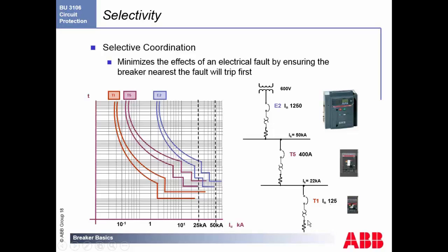Now, if this load down here has an issue, you don't necessarily want to take out the main breaker, because when you do, you are shutting power to all the equipment down the line from there. You can have several different engines, turbines, conveyor belts, what have you, coming off of that breaker. You don't want to stop 5 lines because of a fault on one.